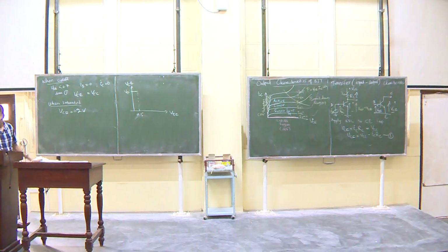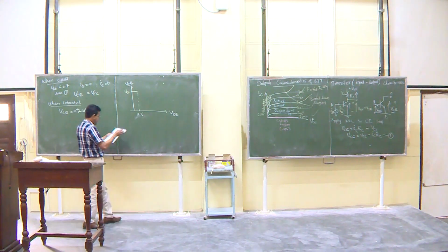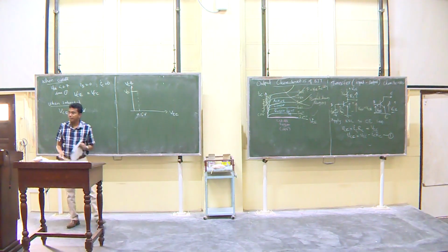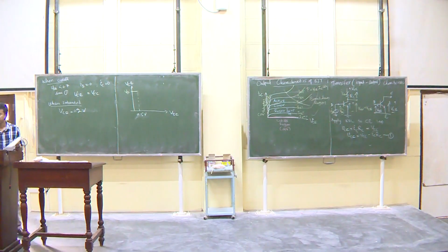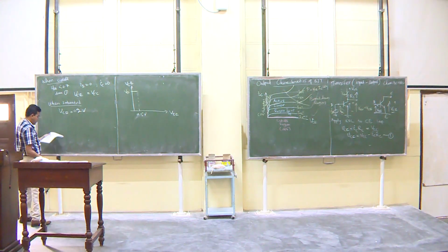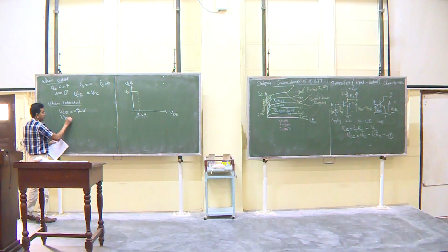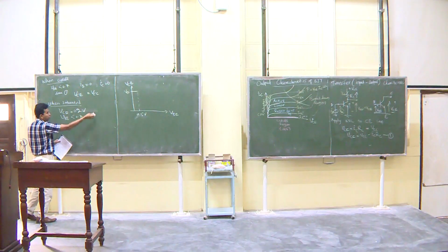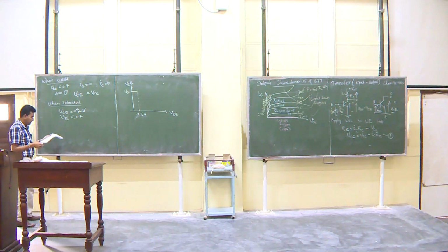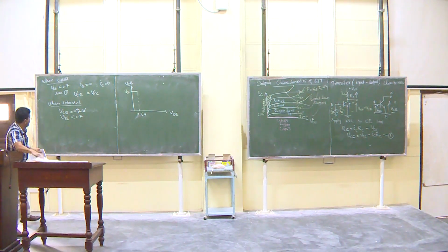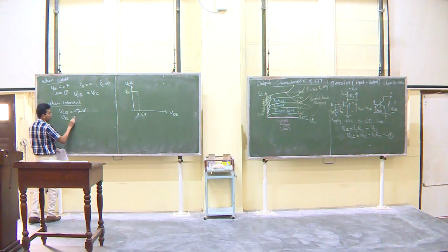Right, got it, agree. This is 0.5 volts, I have up to this, yes, you are correct, my mistake. Right, so now that is also fine. So, therefore, second case is also fine, VBE is less than 0.7, typically up to about 0.5 there will be very small current, and in this case VBE is greater than 0.7.